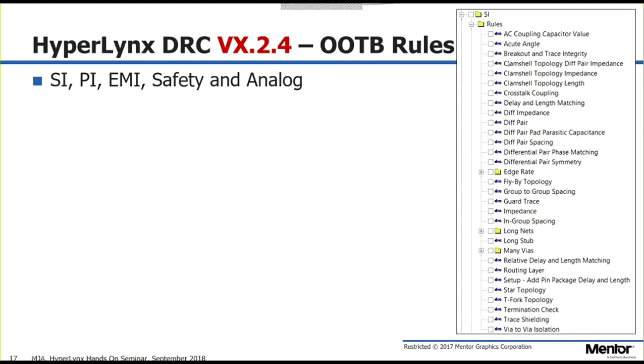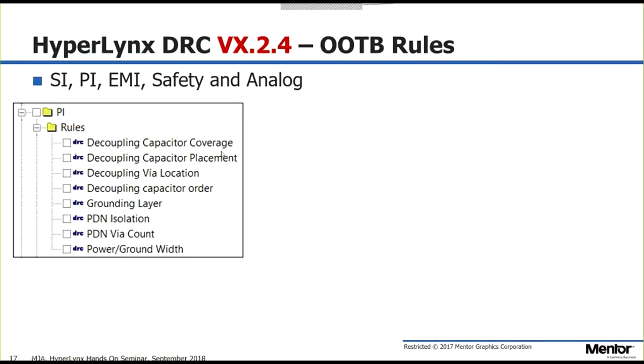So here are some signal integrity rules. So things like looking at differential pairs. Do we just meet the impedance rules that we'd set up? How about symmetry? You routed that differential pair to your routing constraints, but did you actually get them so that they're exactly the same length and they're symmetrical throughout within a certain tolerance range? So, you can look for those kinds of things, other topology settings for things like DDR perhaps. Anyway, a lot of rules for SI. Power integrity, there are some things we can look at there, your capacitor placement, capacitor values. Anyway, a few things there in that space.